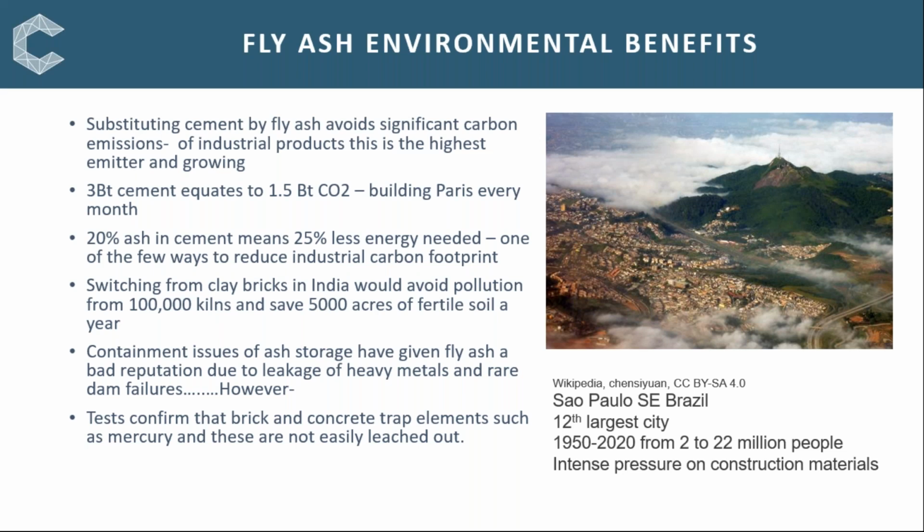These are directly linked to population growth, and the manufacture of cement now exceeds 3 billion tons, and this makes the production of cement the largest industrial greenhouse gas emitter. If you substitute 20% of Portland cement by fly ash, that has a profound effect on the energy use and greenhouse gas emissions of construction. It's one of the few ways of reducing the environmental impact, and of course also means less mining. And with enhanced properties, if structures such as bridges last longer, there's a major gain.